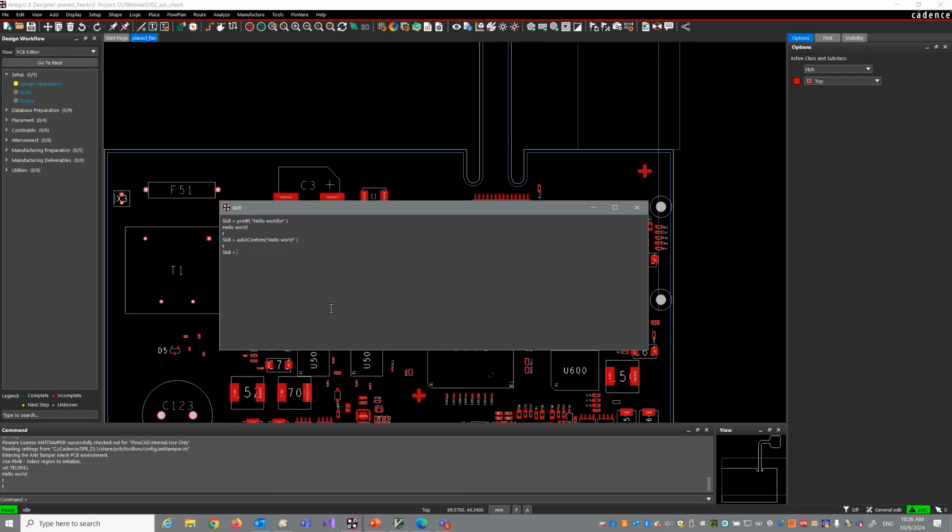There are even APIs available, like, for example, during your pick and place extraction, you want to make a decision and ask the user, do you want to do this or that? axlUIAsk yes, no, and yeah, you have the ability to make a conditional branching. So you can define variables, a equals 3, b equals 4, and then you say c equals a times b, and you will get the result.